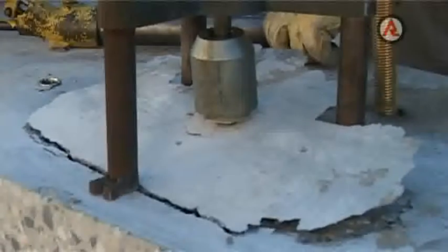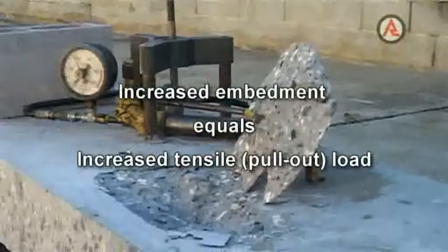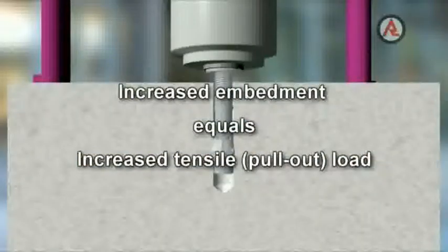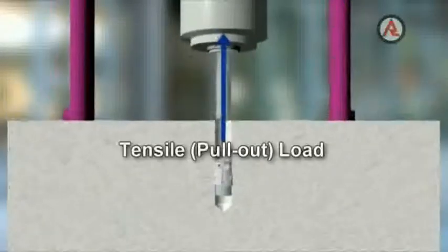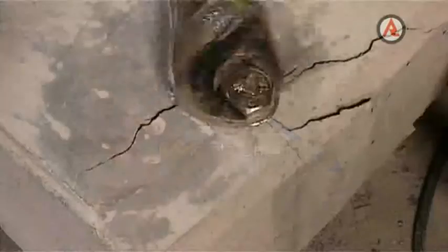In general, this cone increases in size with any increase in the depth of embedment of the anchor. The increase in embedment therefore results in an increase in holding power up to the load-carrying capacity of the anchor, after which the bolt may snap under tensile load. If anchors are located too close together or near to an edge, this coning effect works to diminish holding power.